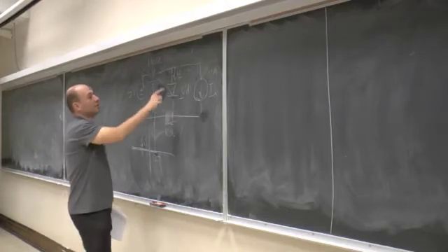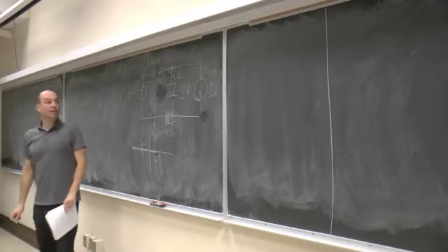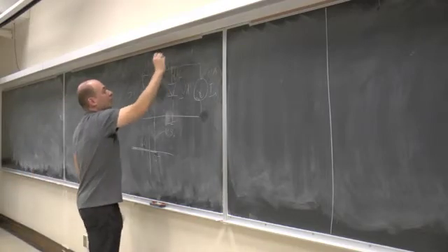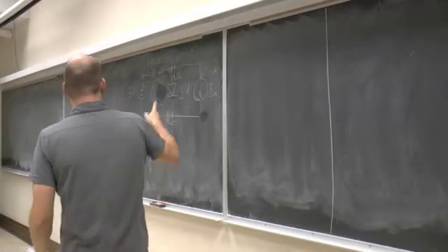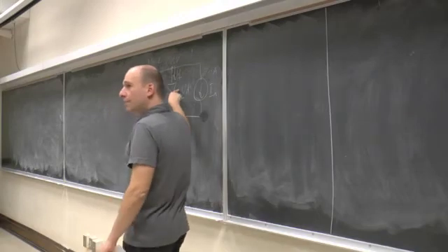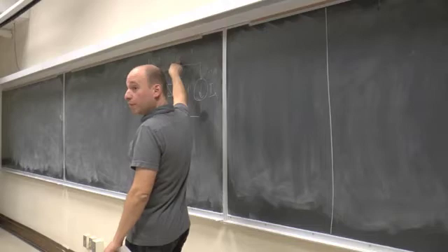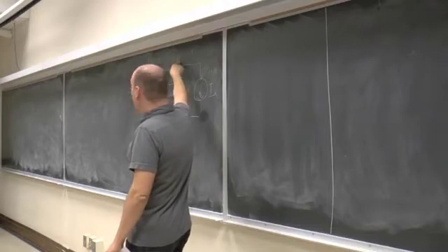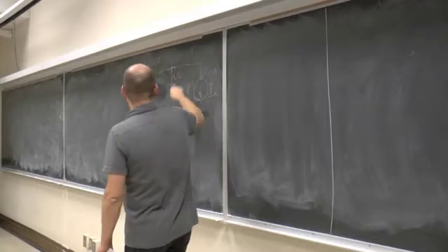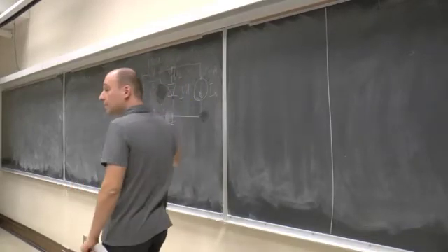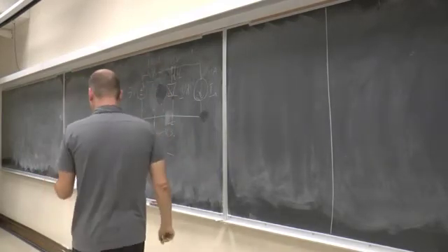So in this case, we can write the node voltage here as what? -2. Okay? All right. And then we check if everything is consistent. With -2, will indeed the diode behave as an open circuit? If you connect -2 volts here, is it forward biased or reverse biased? Reverse biased. So yes, it is an open circuit, right? So there's a solution. If this is -2 volts, this is a consistent solution, right? Okay, so it's turned off.